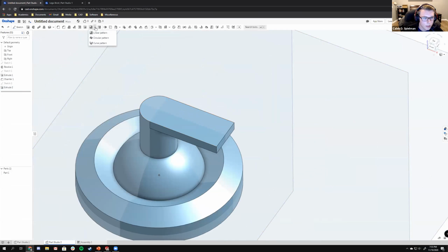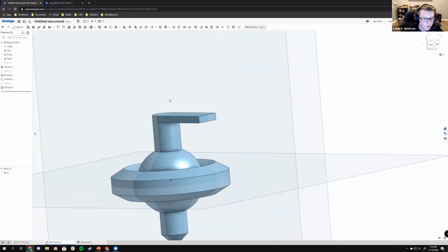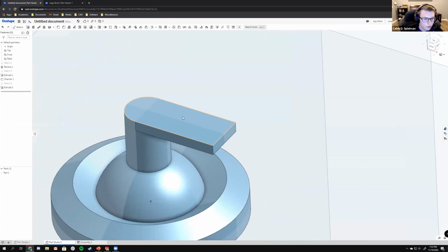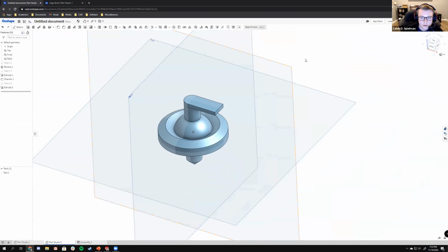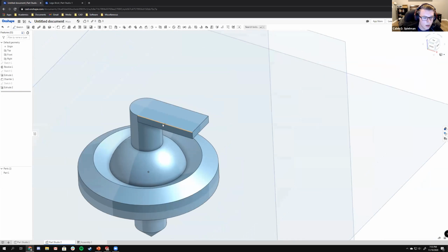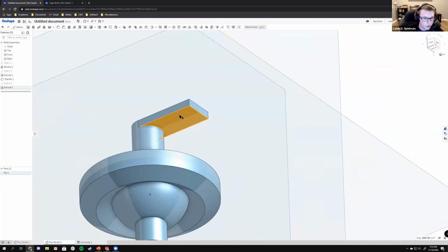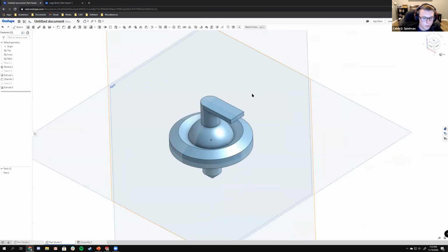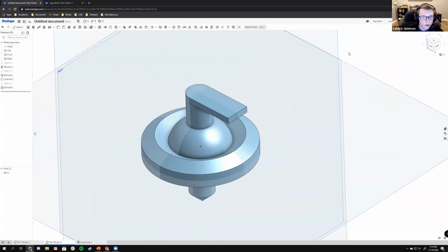So now I'm going to introduce you guys to what's called a circular pattern. I might have to find an axis somewhere, but I'll show you how to do that. So the pattern tools are right below these two links. So here, circular pattern, it does what it says. It repeats a body or entity in a circle. And I'll show you why, but I should not have chosen add here, the common mistake people make, but I'll show you how to fix that.